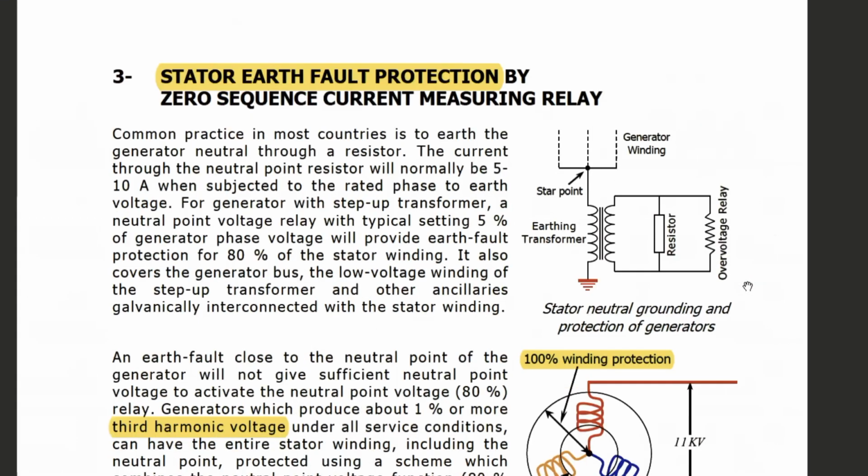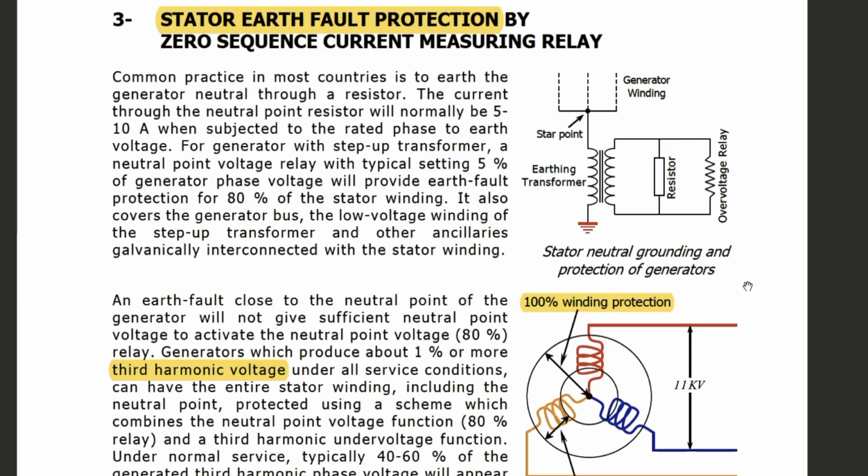And on the stator earth fault, this is also a class A protection. So at this protection, the generator breaker will open, the excitation breaker will open, and the gas turbine fuel will be cut off also, meaning the gas turbine will trip also. So what is the stator earth fault? It means that the stator coil is grounded due to any reason. So it may be a similar fault as with the differential protection.